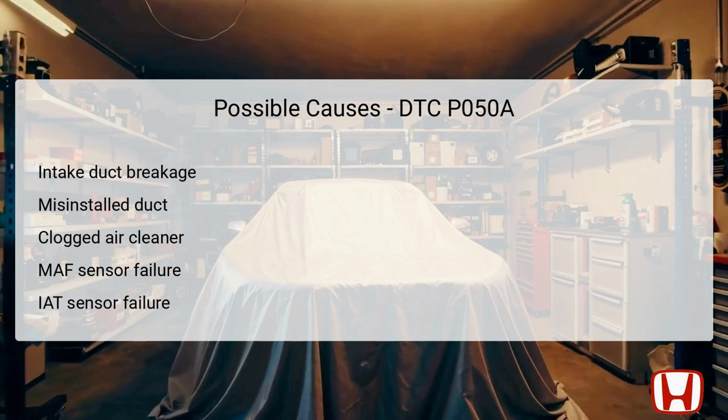Another crucial aspect is the intake air temperature, IAT sensor, which monitors the temperature of the air entering the engine. If it fails, it can lead to incorrect air density readings and poor engine performance. Additionally, any issues with the ignition system can exacerbate the situation, further complicating the cold start process.